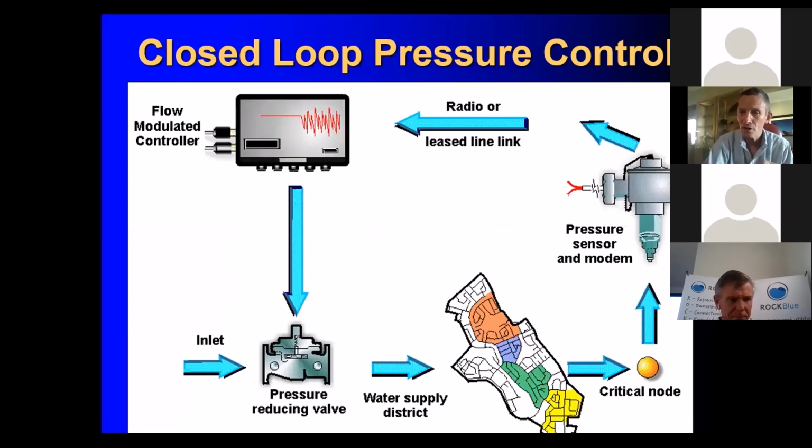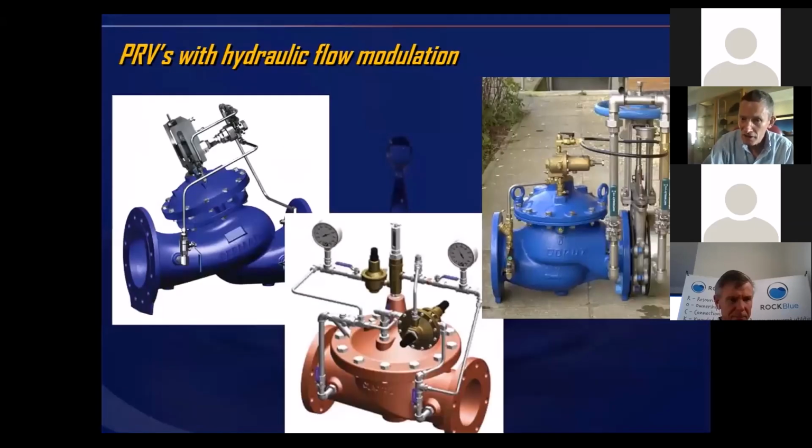You can go for a number of different types of controller. You get hydraulic controllers. There's a couple of hydraulic controllers. Most valve manufacturers have their own hydraulic controllers. They're normally stainless steel, and if you've got a good technical person that knows what they're doing, they can make these things work very well.